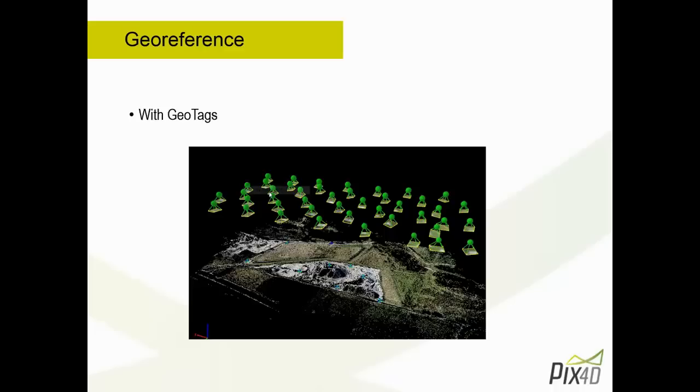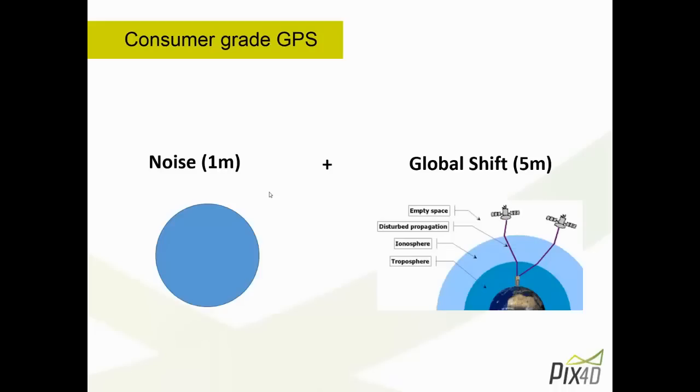Well, this would be good if your geotags were perfect, but in most of the projects you're going to process, especially in the UAV world, this is not going to be correct, because the GPS tag, the geotag that you assign to the images, will actually have a lot of error. It's error because on one side it's very far away from the distance you want to measure, the position of the cameras. In addition, it's very tricky to correctly synchronize the time where the GPS fires and where the camera actually takes the picture. If you take a few milliseconds of mistakes, if you fly fast, this is going to make centimeters of mistake.